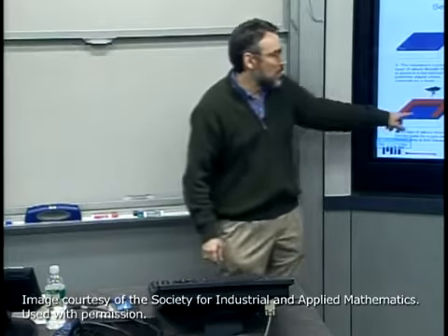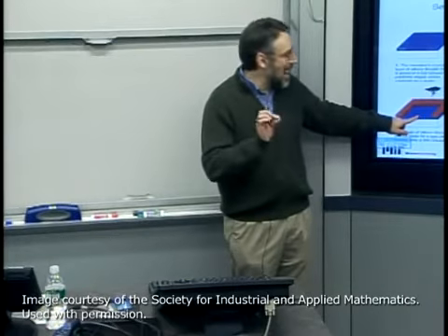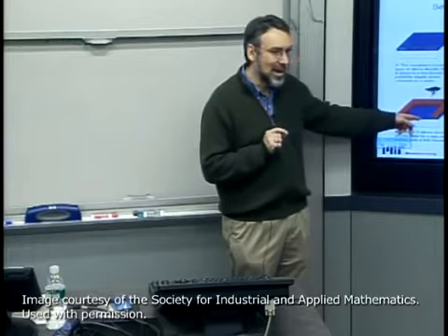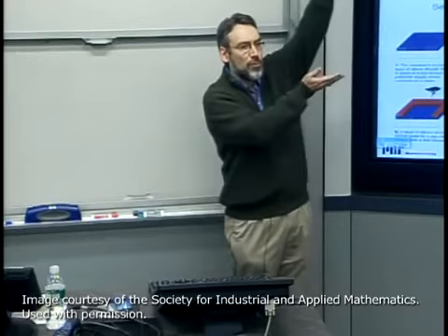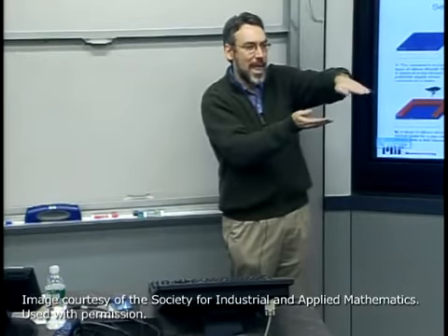What they actually mean is on average over certain kinds of areas. But how would you actually achieve that with the manufacturing process? How are you going to etch down through 5,000 angstroms and stop 1,000 angstroms or 100 angstroms before you hit the silicon? There's very carefully. No, the answer is you're not. You're not.